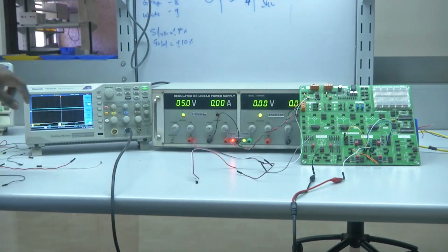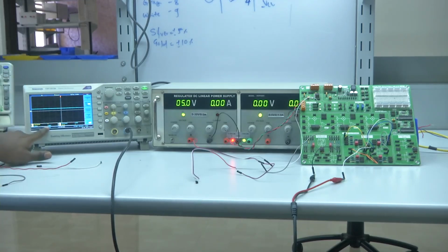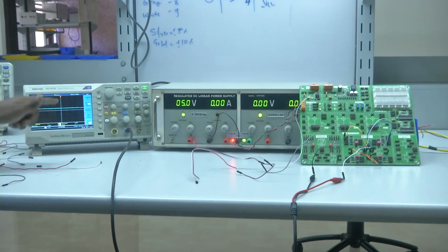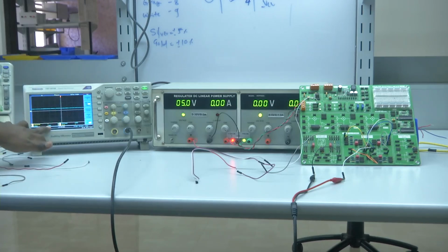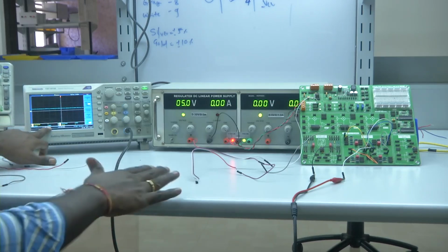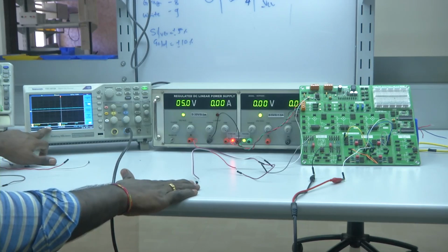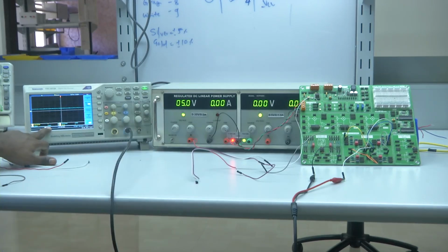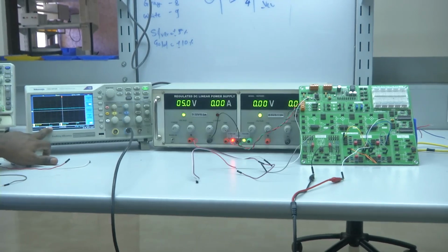Now when we look into the oscilloscope, we can see that the mean value is 2.87 volts. If you recall the complete working of the system, we know that the gain of the system is 10. Since it is not connected to any plant right now, it is at room temperature. The room temperature is around 28.1 degrees centigrade.